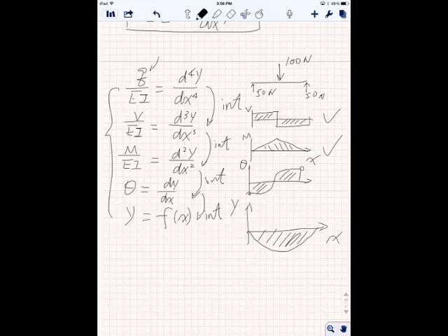So what we did before is we know distributed load will influence the shear force because integration of distributed load equals shear, right? That's what we did. So therefore, if there is no distributed load, the shear force is constant, and then the amount of shear force change will influence the moment because integration of V is M, right? That's what we have been learning.